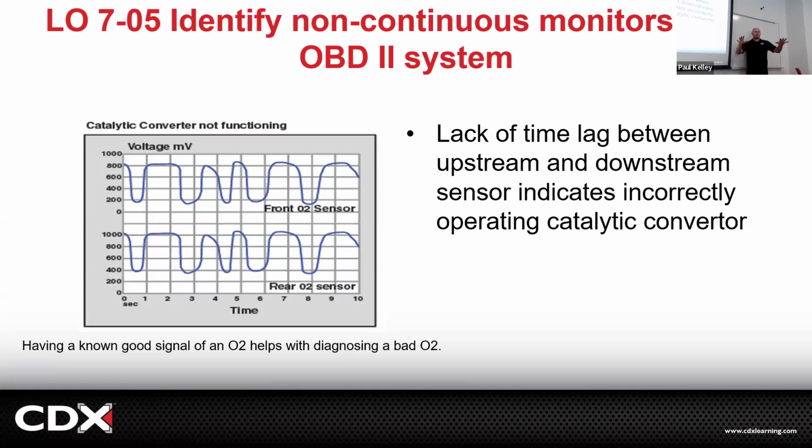So for you guys, we're mostly focused on the initial diagnosis, but don't totally put out of your mind the root cause. This part failed. Sometimes parts fail, but why did this part fail? Is it possible that this sensor is inaccurate, reading more lean than it really is, and telling the ECM to add more fuel than it should? That fuel is going to be very hard on the cat. I don't want to make this dark, but that could kill the cat prematurely.